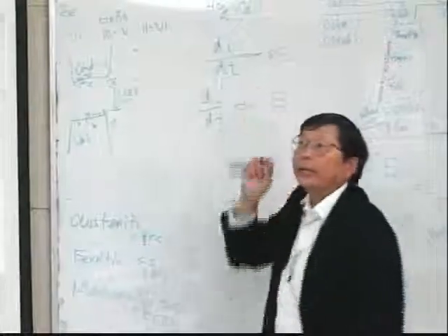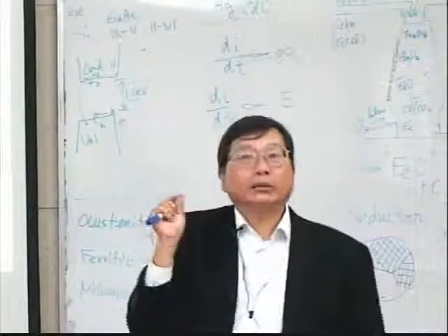So your switch, within maybe 10 times, fuses together. Your switch is no longer a switch. But if you put in some cadmium oxide, then it will not melt together because it has oxide in it. Cadmium oxide is a composite material. That's the reason if you open any switch, you can see that it has composite material in there.